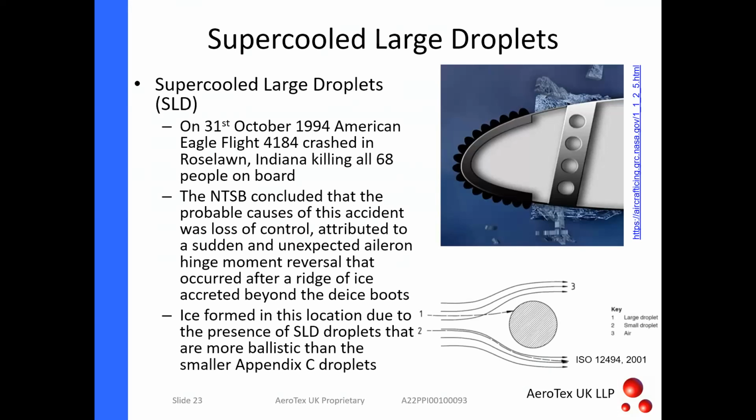This was one of the ATR type aircraft, a turboprop aircraft, so it had these inflatable boots as shown in the picture. And they designed it to these Appendix C conditions that I briefly discussed earlier, which go up to around 40 or 50 microns as a mean diameter.